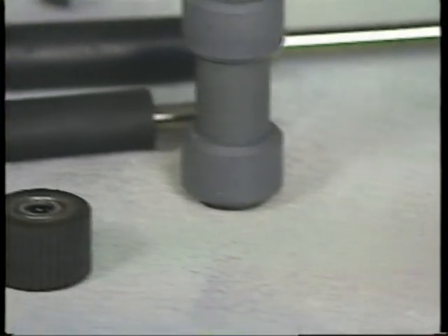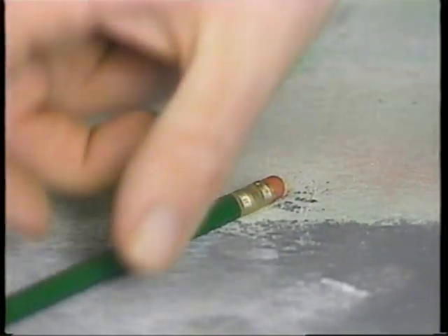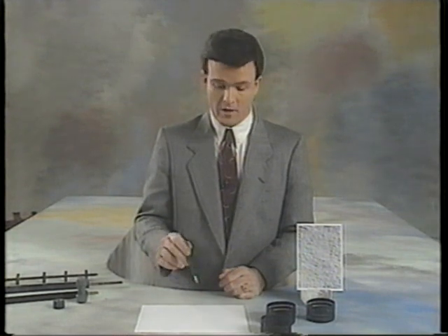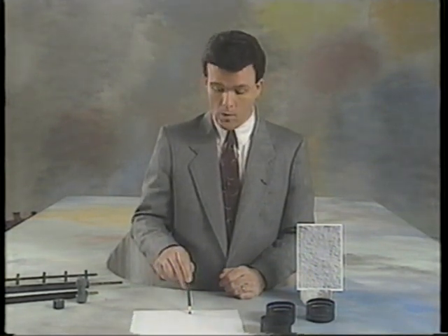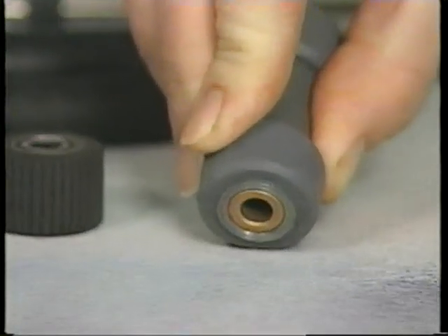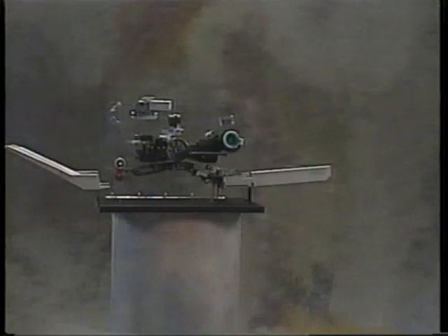If you try to grab this surface with something hard, like metal, you'd run into a few problems, because most of the surface is actually recessed below the top fibers. To move paper effectively, you need something that can mold itself to the irregular surface and create a more secure grip, like rubber. Even this small rubber eraser grabs the paper very securely and moves it wherever it needs to go. There's another advantage to rubber. With a little pressure, it flattens slightly, and the area of contact between the roller and paper increases even further.